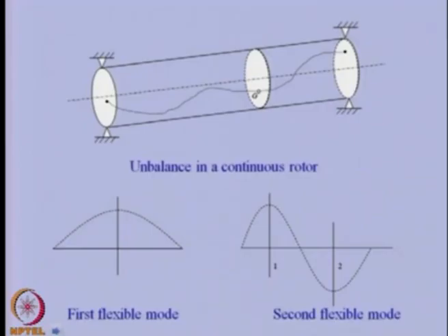This is a long rotor, but this is a flexible rotor. So, you can see that in general the eccentricity will vary radially and also with the angle. In this particular figure the center of gravity is exaggerated just to demonstrate that it can vary like this, but generally the eccentricity will be of the order of microns. You can appreciate that the first one is when the shaft is near the first critical speed. So, we have a half sine wave.